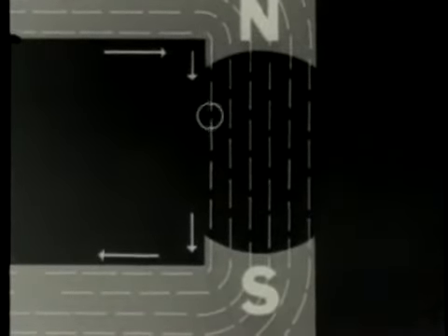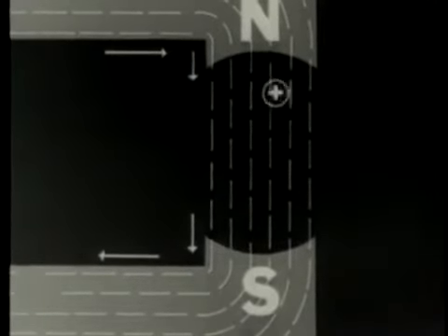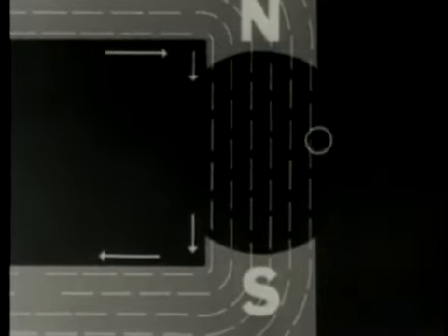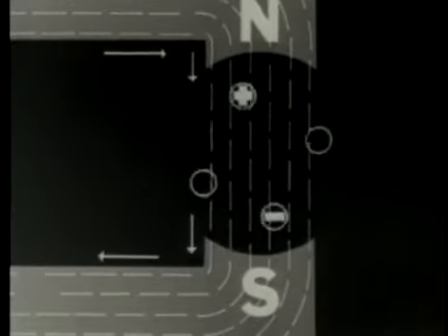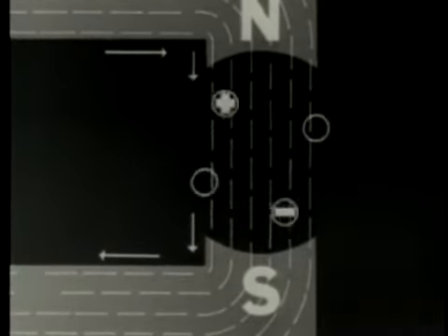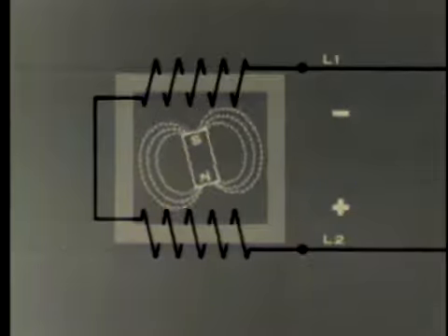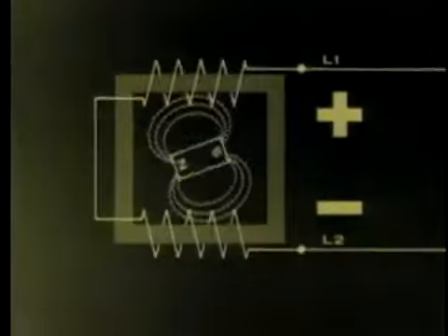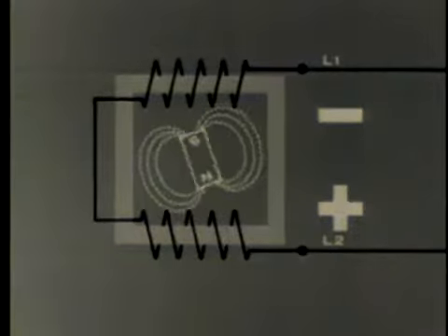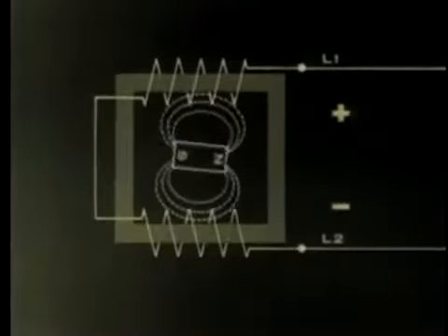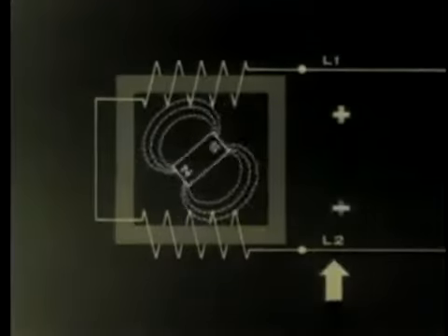If we also concentrate the magnetic field by bringing the north and south poles of a magnet closer, and either increase the speed of breaking the magnetic field or increase the number of wires rotating across the lines of force, we will have a generator. Some generator magnets are located within a coil. Each time the magnetic lines of force of the magnet rotate across the wires in the coil, a potential is induced. Because of the difference in polarity of the magnetic poles, the induced voltage is alternately negative and positive. When we connect this generator to our line, it will create a signaling current, alternating at approximately 20 cycles per second.